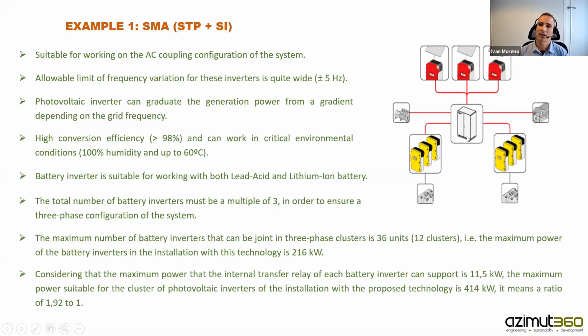So connecting an auxiliary support to each of the clusters would be very complex, many wires, and so this box simplifies the task of connecting everything to this system and conforms the system with all the PV plant and battery inverters to provide to the loads. It has the protections, everything inside, and so it's easy to connect a cluster or exchange an inverter, because all the connections are done in the box, not in the specific battery inverter devices.